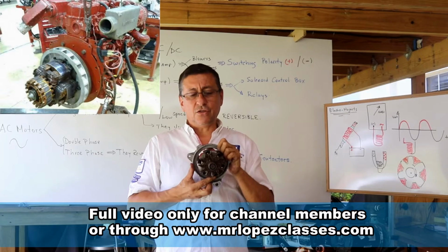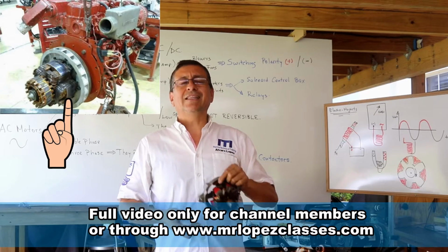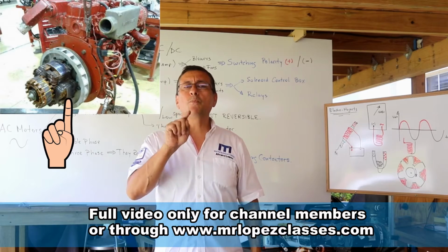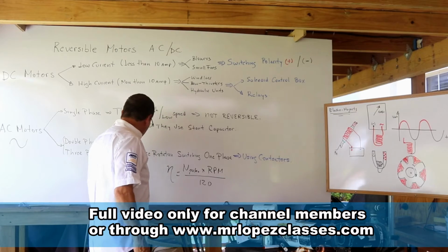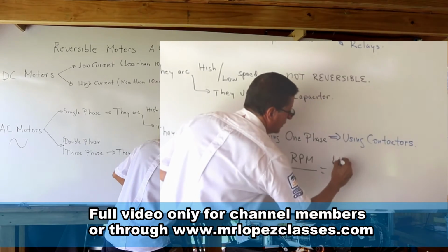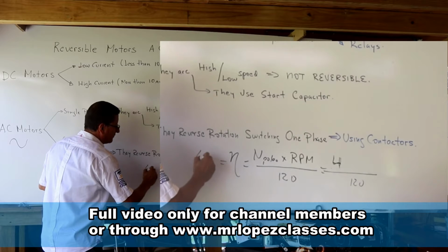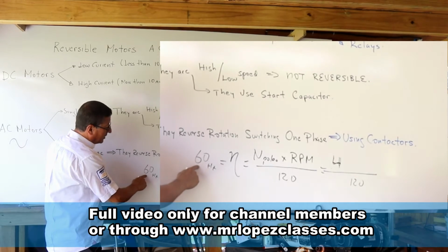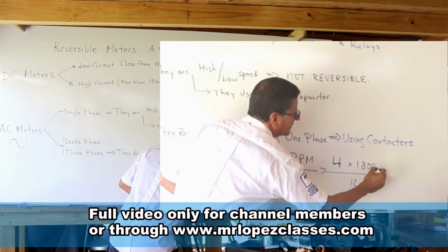There are other alternators with 4 poles, with 6 poles, with 2 poles. The majority of the generators, 99% of the generators, have 4 poles on the rotor. For that reason, if I have 4 poles in the rotor, in order to get 60 Hertz for American power, 60 cycles, each cycle is 1 Hertz, I need 1800 RPMs.